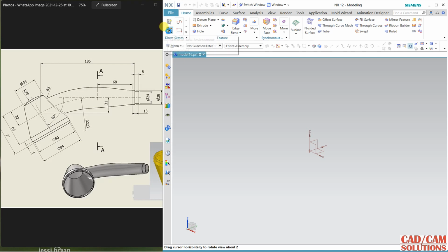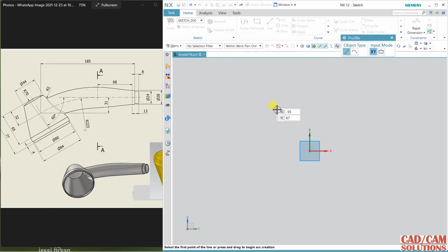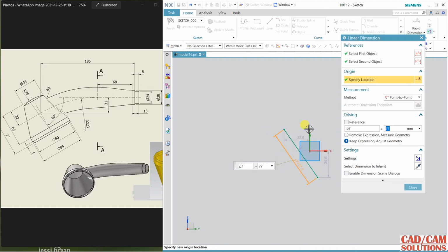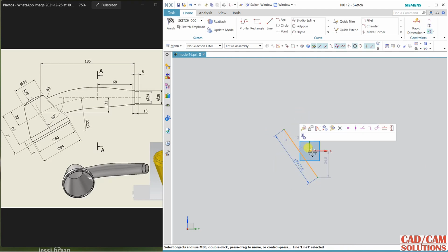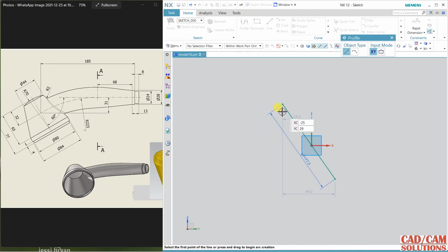So here select this sketch, and I'm going to create it from this YZ plane and draw a line. So I'm starting from here. This is my center line, which is 77 in length, and align this line to the origin, make them point on curve. Okay, now select this profile, and I'm clicking here and a little bit perpendicular, then taper